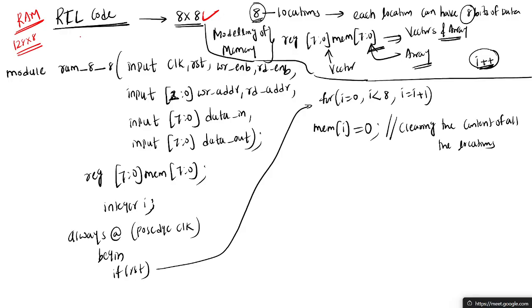Should modify it with parameterized. Yes, we need to use the parameter concept. So here you need to write the code with parameters. I will add parameter width. Width is 8 only. And parameter depth. Here itself I can change the depth to 128.